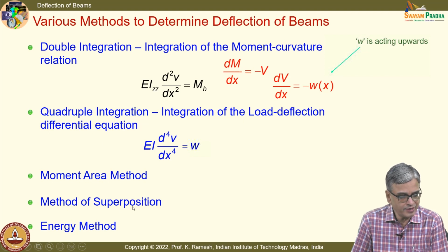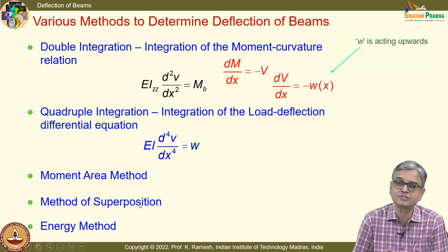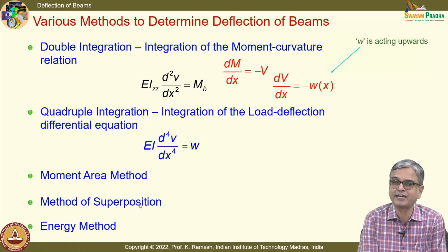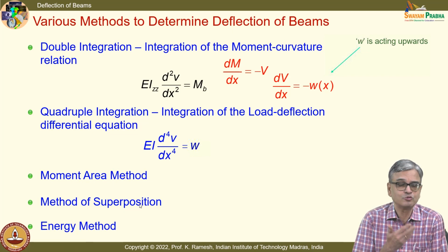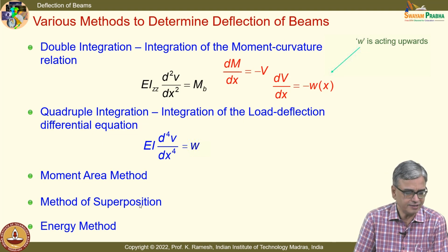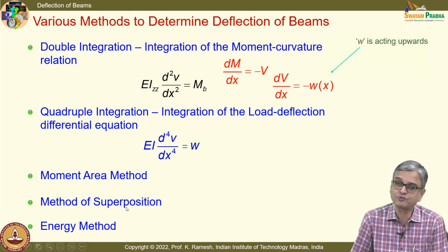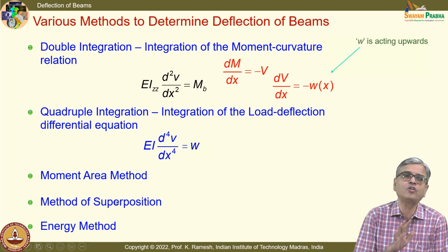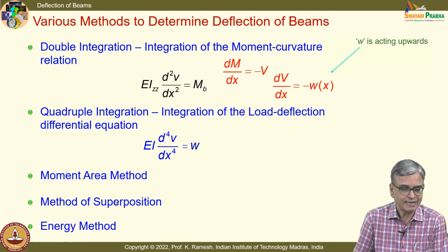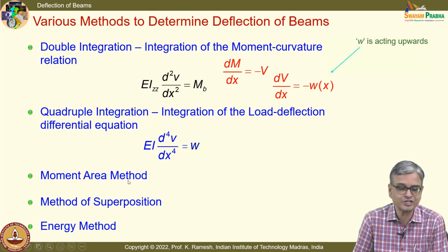And we have always been saying that we are going to use the principle of superposition left and right in this course. We have used linearized elasticity, and it is an isotropic material. And when you have the advantage, why not use the method of superposition? In this course also, we would emphasize more on the method of superposition rather than this double integration or moment area.